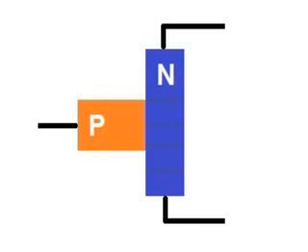Now, you may be thinking, hey, this whole thing works by reverse biasing the gate. It's just sort of a diode. Can I forward bias the gate and one of the channel terminals and use it as a diode? Well, yes, you can, but it really isn't designed for that. A forward bias current larger than about 50 milliamps will destroy the transistor, so if you need to use it as a diode, just get a diode.